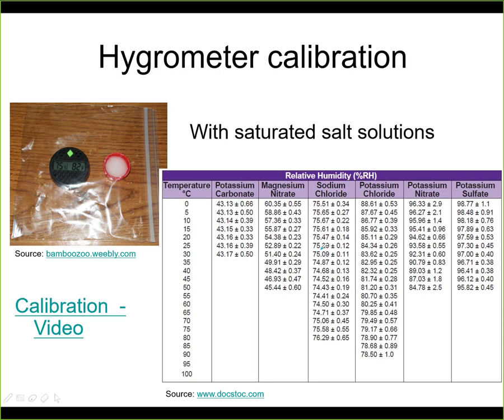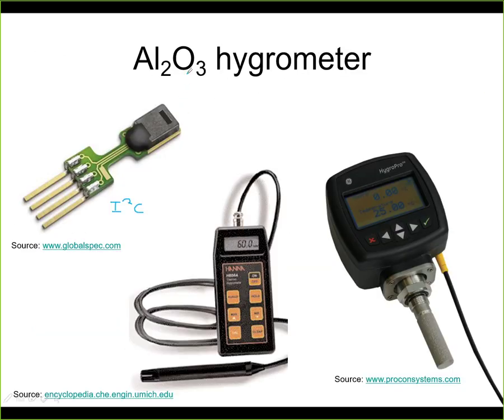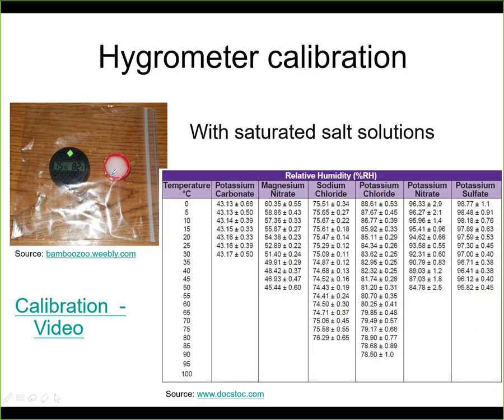The hygrometers that we can calibrate like this are typically looking like this, as say normal household hygrometers, and they measure with an accuracy of plus minus 5% anyway. I forgot to tell you the accuracy for this kind of hygrometer is typically a few percent. So a chip like this, even the most expensive ones that you can get, they will measure within, let's say, plus minus 2% approximately. And the normal ones, the cheap ones, will be something like plus minus 5, plus minus 8%. So it doesn't make sense to calibrate the hygrometer within 0.1% because the sensor is not able to measure it anyway.